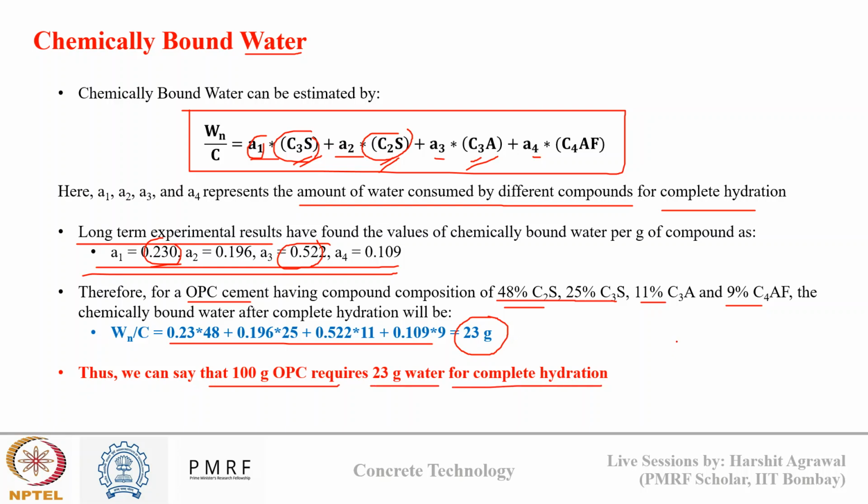However, when we prepare concrete, we generally use a higher W/C ratio of say 0.3 or 0.4. Why is that so? Because we want initial workability and flowability in the system. If we take just 0.23 as the W/C ratio, then my cement paste won't be workable enough to be made into a proper shape, or to pass through a pipeline from the concreting side to the molding area.